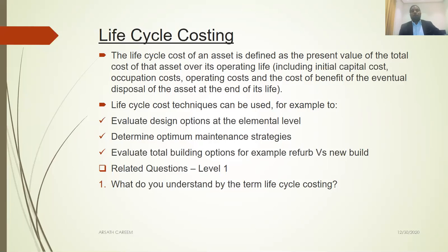So you should know the construction part. Until you build the building, your part is finished, but still there is a cost: operation cost, maintenance cost, dismantle cost. So you as a designer should consider this as well. Sometimes when you design, if you consider only the capital cost for a particular item, at a later stage you might have an operation and maintenance cost more than that throughout the lifetime of the building. That will cost more to the end user or client.